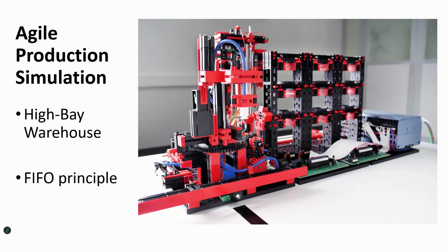stations that in the APS model have their own vacuum gripper. So what's going to happen here is the vacuum gripper will take the workpiece, pick it up from the AGV at the docking station. There's a little docking station here, and it will hand the workpiece over to the stacker crane where it is then stored. Well, actually, before it's stored, it's placed in a workpiece carrier, and then it's stored.